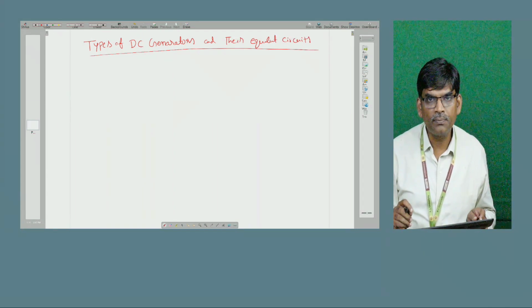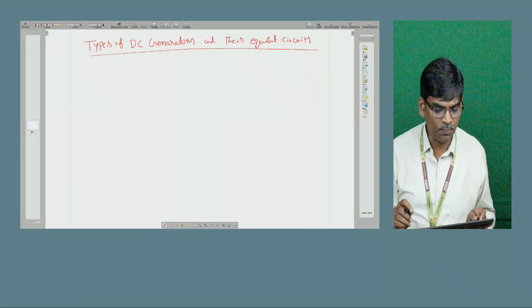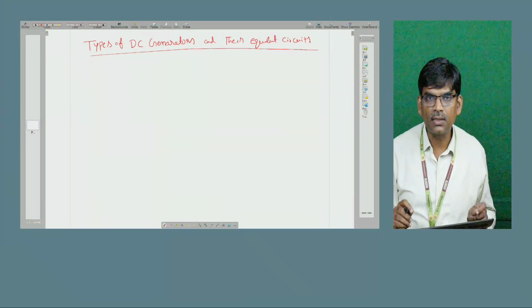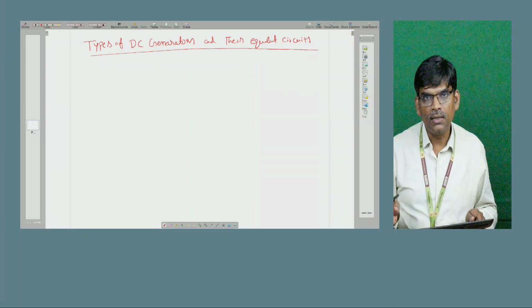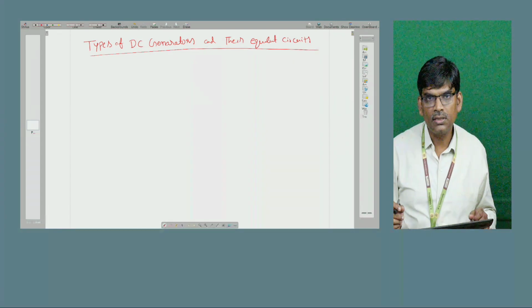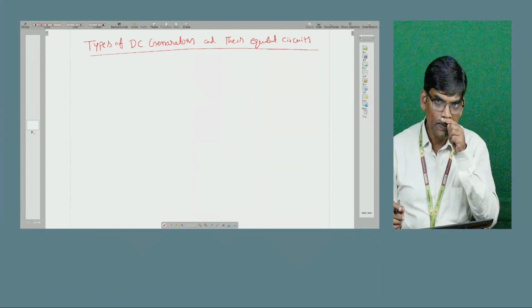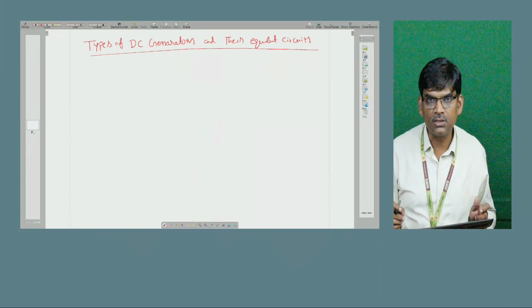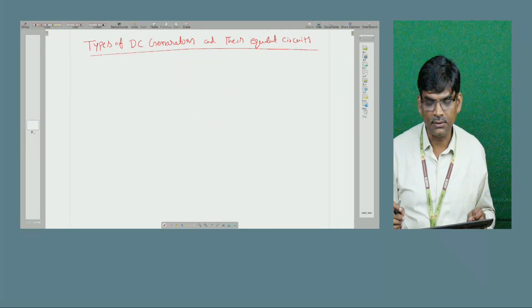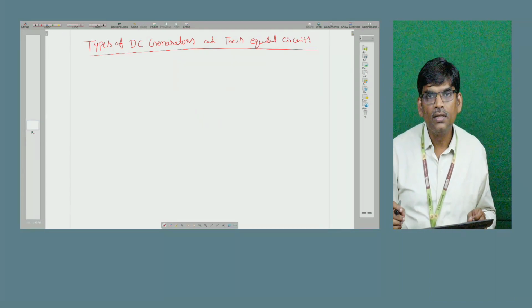On the inner periphery of the stator, magnetic poles are provided. On those poles the field winding is placed. Maybe all the coils are connected in series to form one winding. But to develop a voltage, you require magnetic flux. The magnetic flux source is either permanent magnets or an electromagnet. So here the field winding is used to set up the magnetic flux.